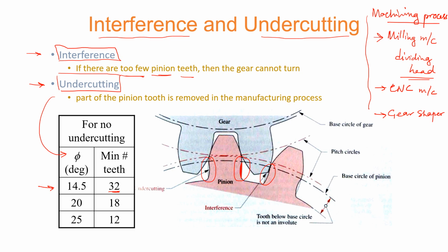You have the gear machined using a tool which is also gear-like, and in a controlled, iterative, repeated machining action, it incrementally removes the material, allowing the machine to perform these increments in a careful fashion in order to shape the involute gear profile. Generally these are the machines used for the machining.